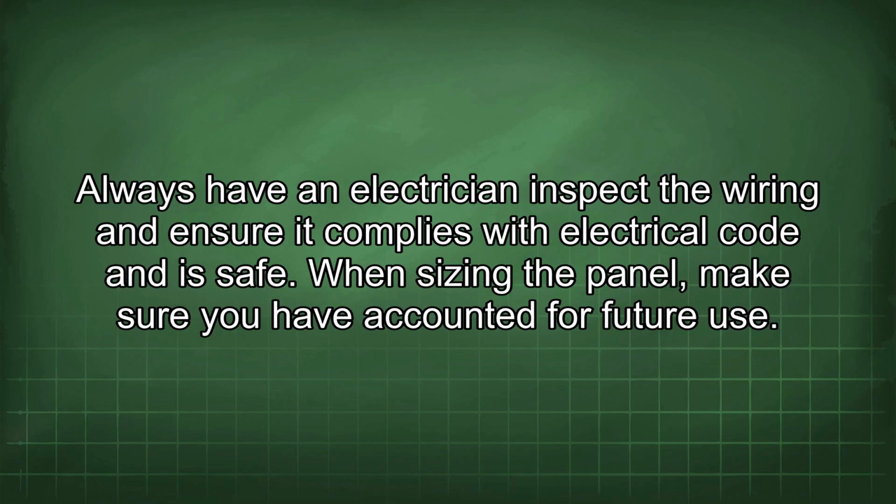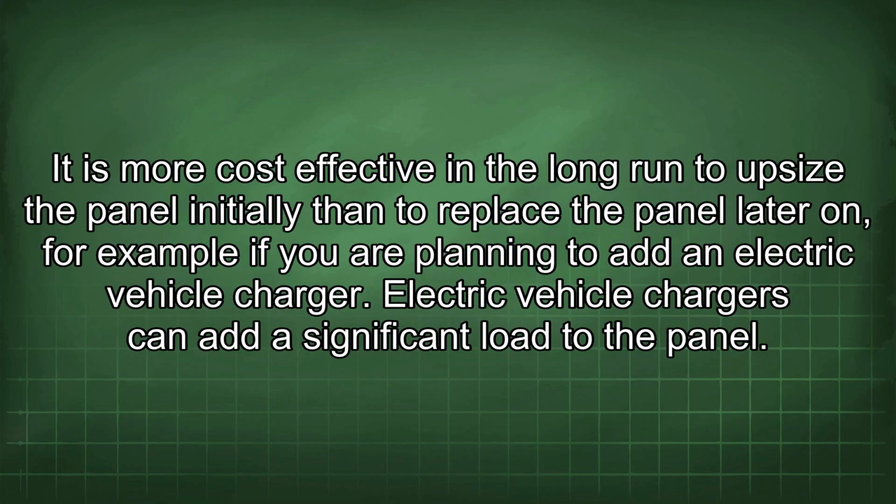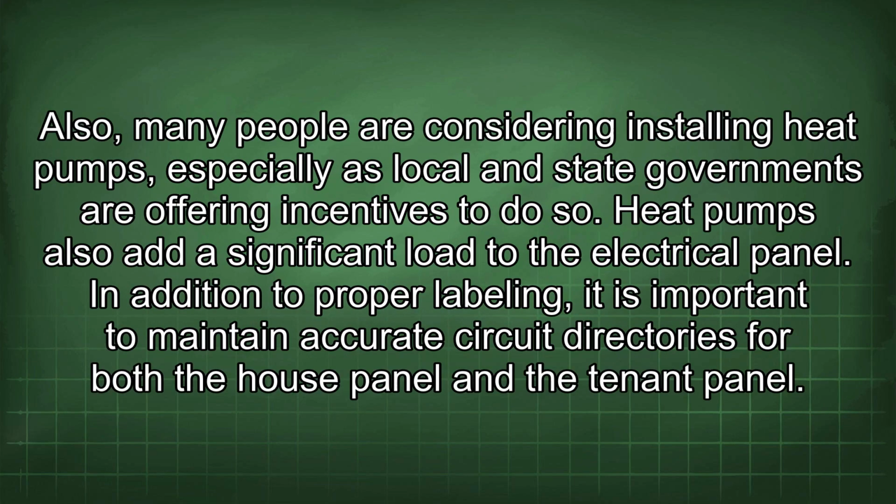When sizing the panel, make sure you have accounted for future use. It is more cost-effective in the long run to upsize the panel initially than to replace the panel later on, for example if you are planning to add an electric vehicle charger. Electric vehicle chargers can add a significant load to the panel. Also, many people are considering installing heat pumps, especially as local and state governments are offering incentives to do so. Heat pumps also add a significant load to the electrical panel.